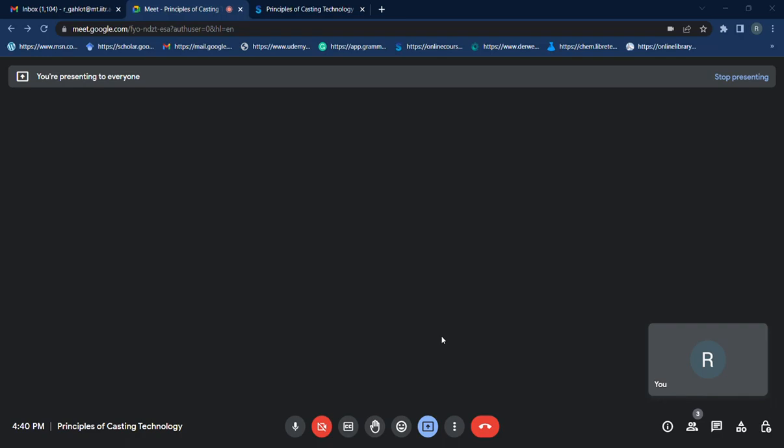Whenever these types of problems come, firstly, if anything is written about investment casting, it has the best surface properties compared to the conventional processes. Nowadays, processes have come which are better than investment casting, but generally investment casting has a good interior and better properties than the others. So you can directly match D with 2, since parts have hardened skin and soft interior, and nothing else mentions a soft interior.